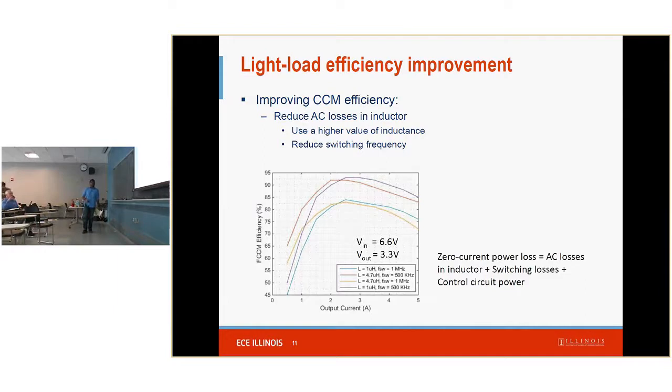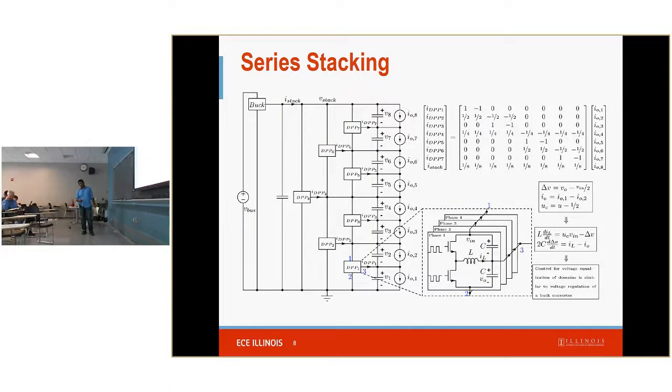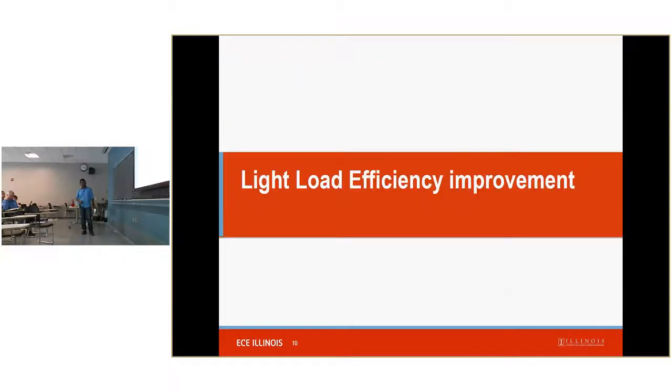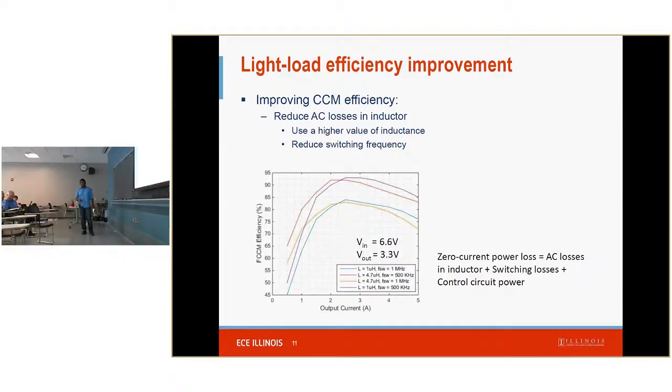The synchronous buck stages that we had over here can be controlled by just complementary PWM, and if we allow the inductor currents to change directions, then we can operate it in a bidirectional fashion. Improving CCM efficiency, if we are operating the DPP converters in forced CCM mode, is quite difficult, and we are not going to get enough improvement out of it.